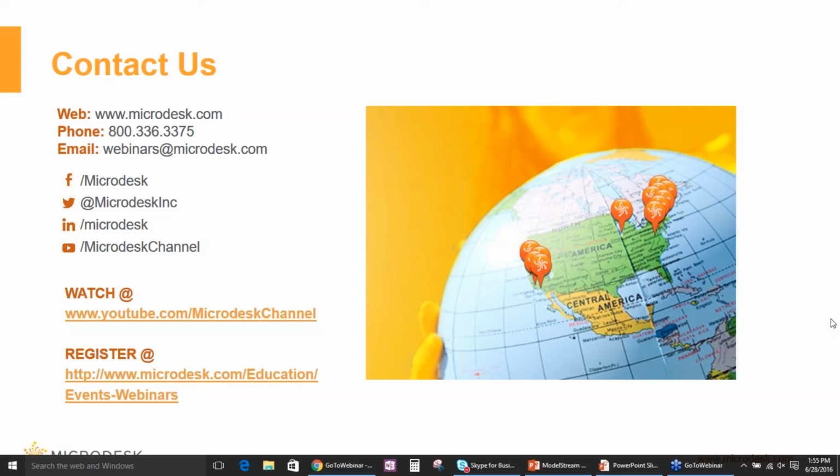And Brandon, this is for you. When you said you get these by the web version of Revit, what did you mean by that? I was referring to the web model, as I had mentioned, or the WebGL compatible format of the model, which is using the Autodesk large model viewer. When you translate the Revit model into that WebGL format, you get the Revit properties with it, and that's what I was referring to.